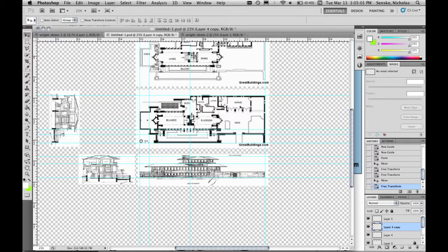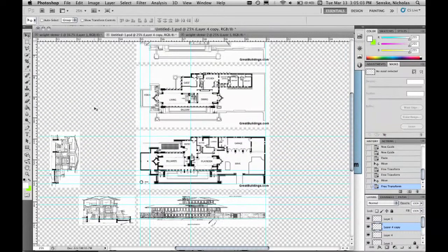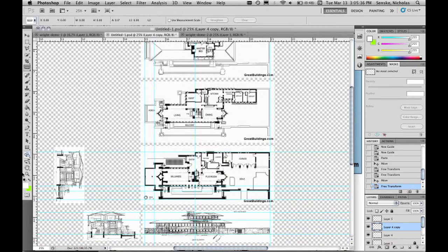Again, if we were really, really careful with it, we could take the measure tool and measure something here and something there, and then do a proportional transform. But I think doing it by eyeball is fine. As long as you say, okay, I'm going to base all my things off of the one plan, and then everything is going to spring off of that, and everything off of this elevation, as long as it lines up with the plan, that's going to override my section. Section's just for information. It's not going to be for measurements. Okay? And that's okay. You just have to stick with something.